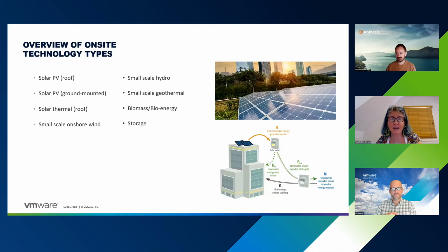Okay, yeah. Thanks. I would also say that typical data centers are running in the megawatts, so 10, 20, 30 megawatts, even more if you're talking about the hyperscalers. And an on-site system of even a megawatt takes a huge field of solar array. So the likelihood is that you're not going to be able to cover 100% of the data center's power consumption, or maybe even a fraction of it, with on-site solar.